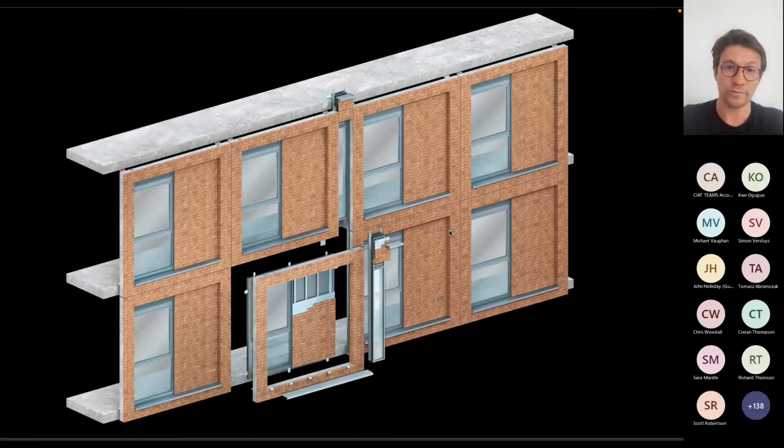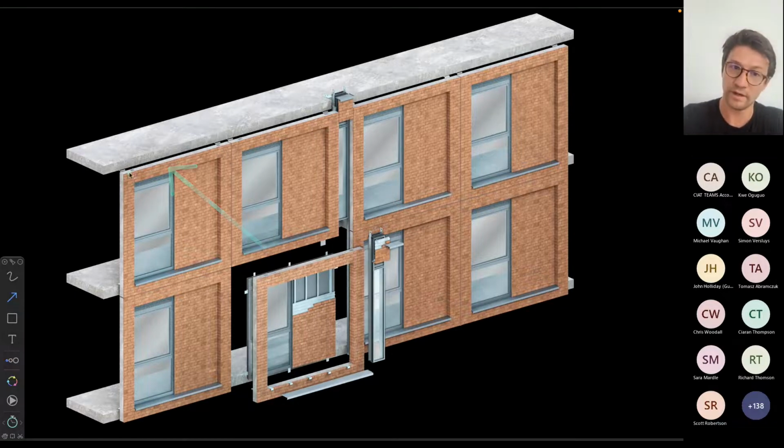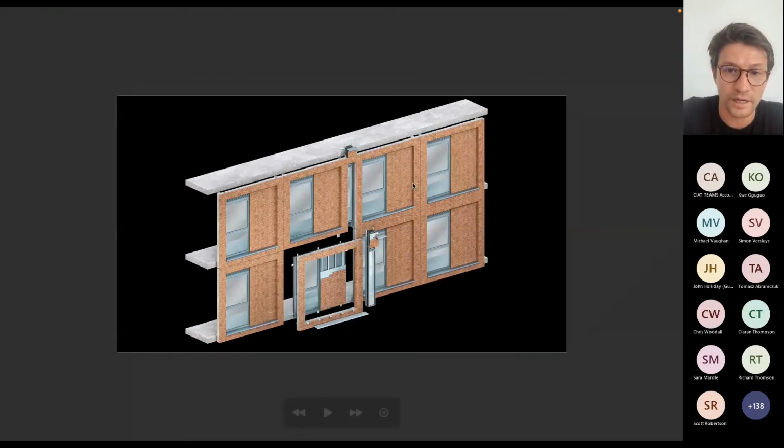What we have here is a precast concrete assembly with the windows fixed to it, but because we have a very thin wall requirement, we still need to get the recess. We have brick slips here, and in order to achieve a certain fenestration, where we have slit windows, we will have to use a unitized facade with the brick slip fixed to it. And let's discuss how we got here.